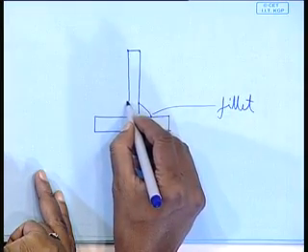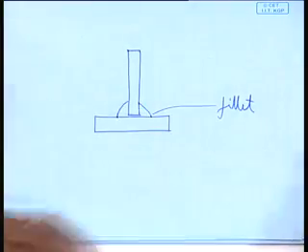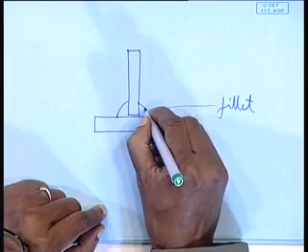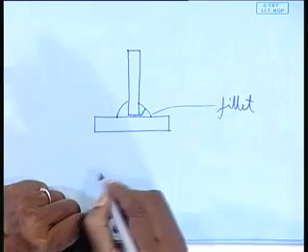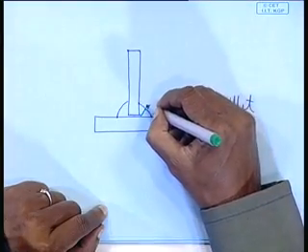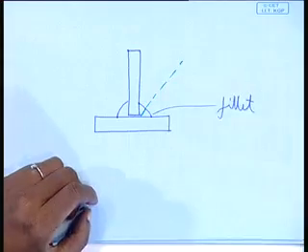So, both sides welding was done. After it's still hot, right? That means welding has just finished, and immediately you see a through and through crack forming at the middle, all along the length. So, that is what is referred to as hot crack.